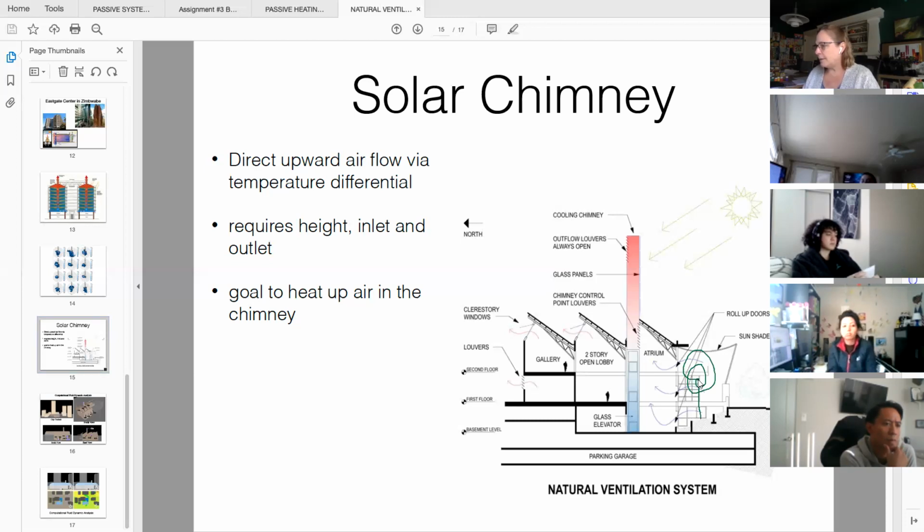We analyzed low-E double glazing, non-low-E double glazing, and single-paned clear glass, and looked at how they would perform at different times of the year. The single-paned clear glass worked the best in the winter to keep the most heat in the space. And so that's what we installed, which was great for the budget because it's a lot cheaper.